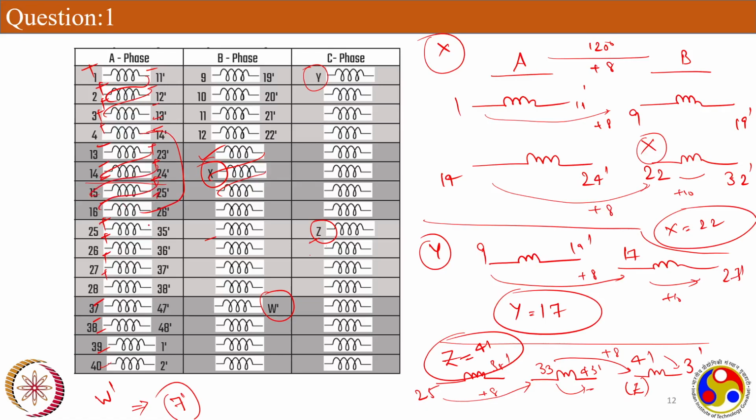So again, next come back to this one. First add coil groups within, and then you will be left with this particular coil, this is one, and this will be negative, and you go with adding it with the positive here. Okay, and then you will be having another negative. In that way you have to proceed if you want to calculate the voltages.